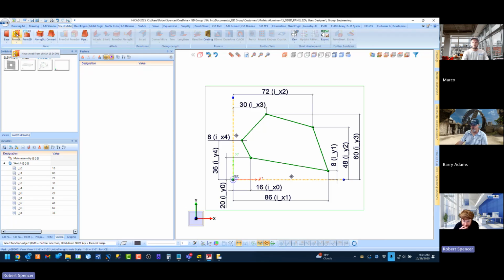So when you go to element installation to use this, in the background it's going to take those sketch lines and measure those lengths and feed them into the variables of your variant of your catalog file, and that's how the panel is going to adapt to that unique shape from the elevation sketch.